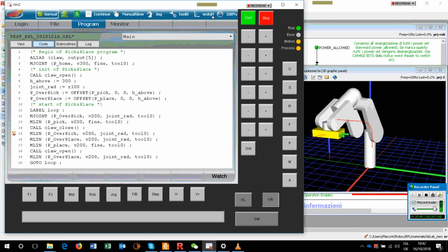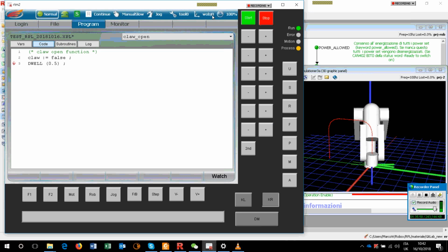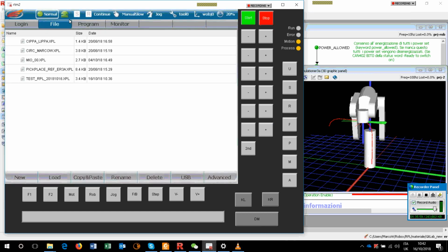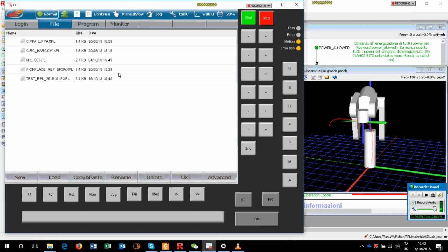Now we stop, we let it finish, and never leave the robot with the product in the cloud. Okay, I stop. Stop here, okay? I take out this, and I say, File. The program is automatically saved when you go out from edit, but sometimes you click Save, which is better. Then, on the CPU, you can put a USB pen. There is the little rubber part.